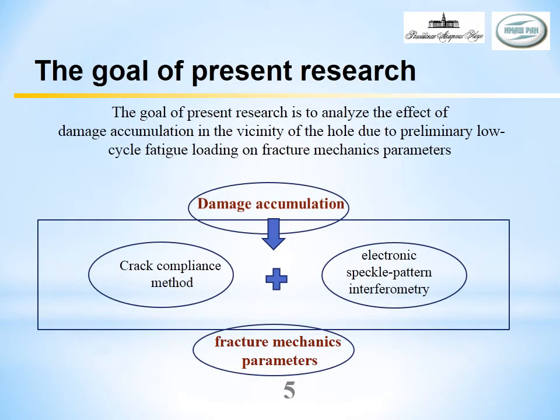So, goal of present research is to analyze the effect of damage accumulation in the vicinity of hole due to preliminary low cycle fatigue loading on fracture mechanics parameter. After preliminary low cycle fatigue loading, consecutive narrow notches emanating from the hole are performed under the constant external load for each specimen to estimate the effect of damage accumulation on fracture mechanics parameters. A measurement of deformation response caused by local material removing in the form of a notch is carried out by electronic speckle pattern interferometry.